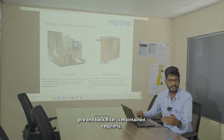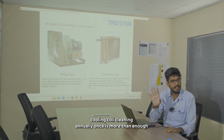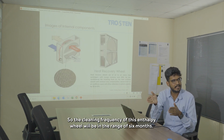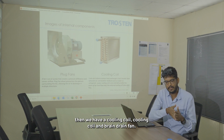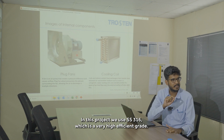Then if the pre and back filters are maintained regularly, cooling coil cleaning once annually is more than enough for us. Yearly once, I am saying. So the cleaning frequency of this enthalpy wheel will be in the range of 6 months. Then we have a cooling coil and drain pan. The drain pan in this project is SS316.